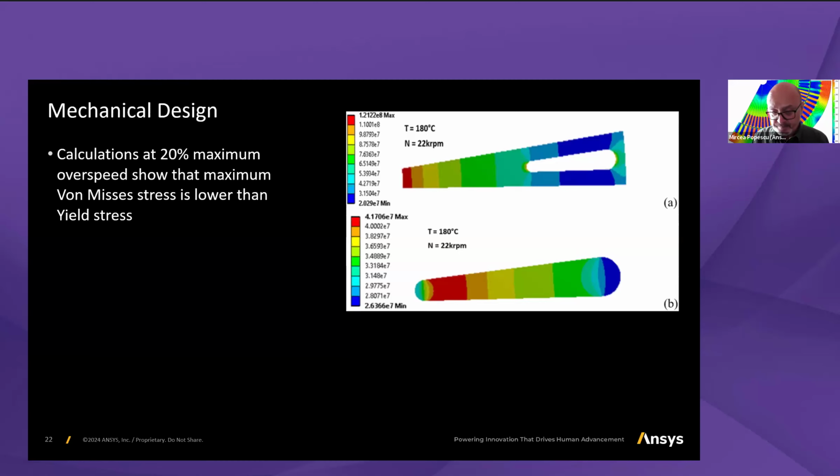And you notice the rotor bars are closed, and the mechanical stress analysis show that they can withstand easily the effect of the centrifugal force on the rotor lamination, including the effect of the end ring of the rotor bars as well. At a very high speed here is reported at 22,000 RPM.